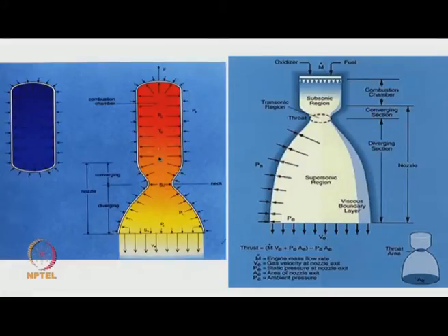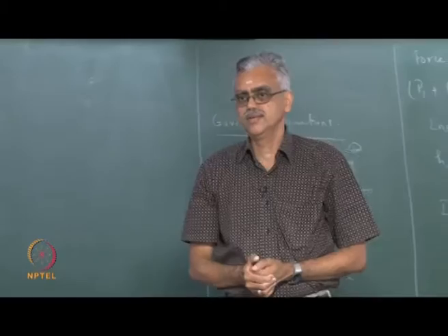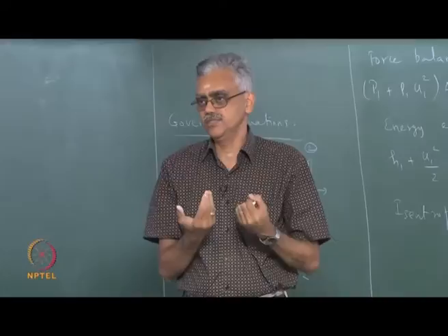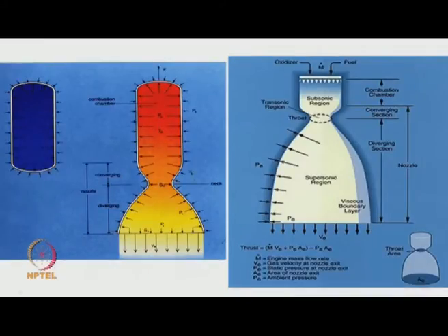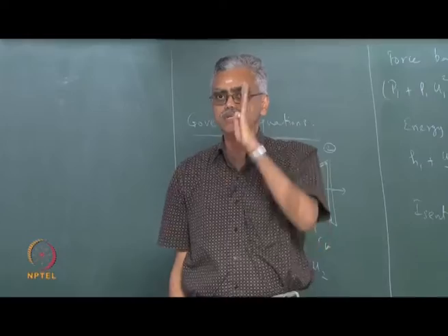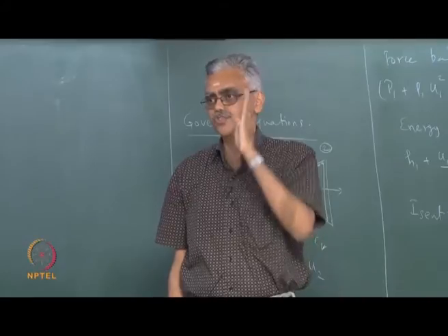It is quite interesting to see from this that, remember, if this were to be used in a rocket, in which direction will the thrust force be developed? Thrust force should be developed upwards, correct? But you notice that the convergent portion of the nozzle actually develops net thrust force in the opposite direction. So, the convergent portion of the nozzle actually produces drag. It is only the divergent portion of the nozzle that produces thrust, because after I subtract this ambient pressure from these arrows, now I have a substantial component in the flow direction which produces thrust.